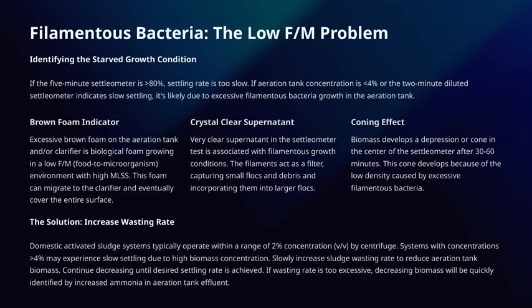Another visual clue to watch for is the brown foam indicator. Excessive brown foam on the aeration tank or the clarifier surface indicates biological foam growing in a low FM environment, especially when the MLSS levels are high. This foam can migrate across the system and eventually cover the entire clarifier surface, disrupting normal operations.